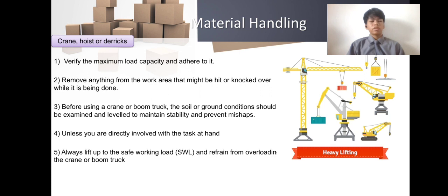So for safety, don't use your hand or touch anything on the crane, because the crane may be in a condition of hot or sharp objects, so don't use a hand. Always leave a safety margin for the SWL and prevent overloading the crane or boom truck.